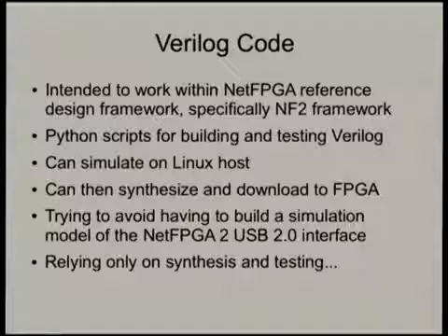The Verilog code is intended to work within the NetFPGA reference design framework, specifically it's called the NF2, the NetFPGA 2 framework. It uses Python scripts for building and testing the Verilog, can simulate on a Linux host, so all their development was done on Fedora-based devices, and they have a complete simulation environment there. But it's again using proprietary Xilinx tools which do run on Linux. And then they have a synthesize environment to download the code across PCI onto the FPGA on the NetFPGA card.